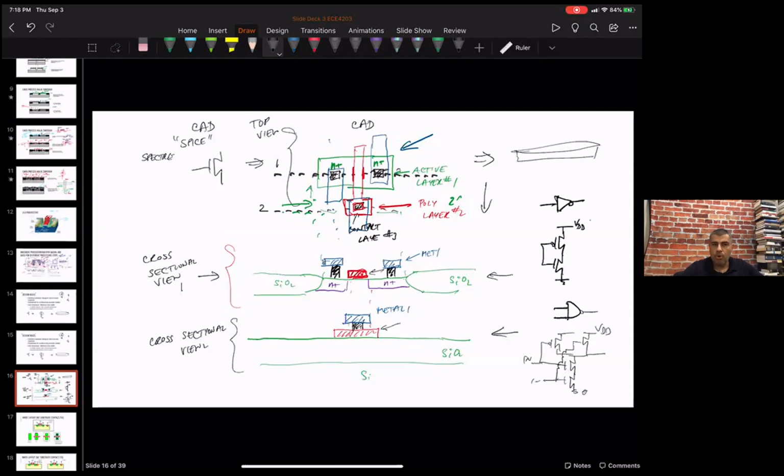Let's say you had a metal 2 over a metal 1, there's a dielectric between them, so you could draw a metal 2 over a metal 1 and they wouldn't short with each other unless you put a contact layer down. Or a metal 3 wouldn't short with a metal 1. It's called escape routing, because you're trying not to paint yourself into a corner.